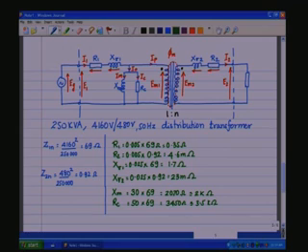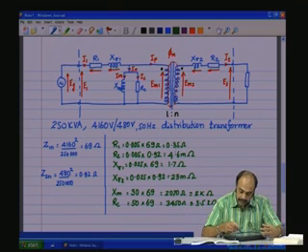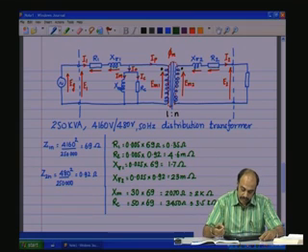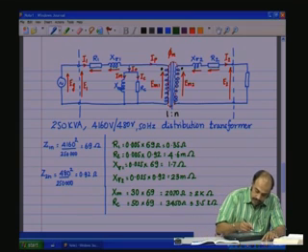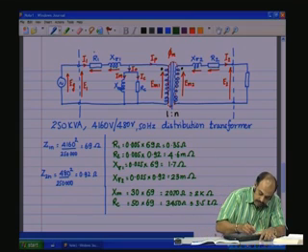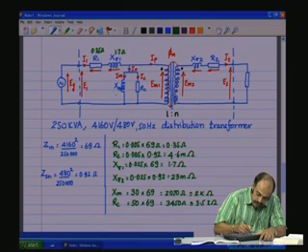Now, these are the real impedance values, at least the order of magnitude or approximate values of the real impedance values of the transformer, which we can now write here. This is having a value of 0.35 ohms, having a value of 1.7 ohms. This is around 2 kilo ohms. This is around 3.5 kilo ohms.